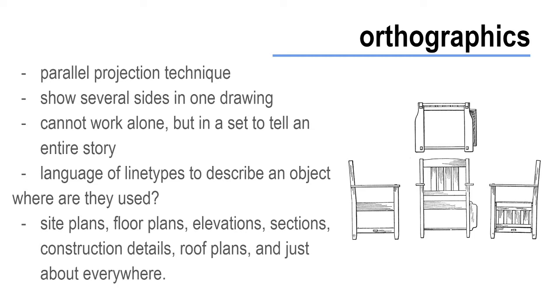Traditionally, it is 3 views: our front, our top, and then a single side view. We can unfold an object to show 6 views in total. All objects have a front, a back, a right, a left, a top, and a bottom. So you can show 6 different sides of something, but traditionally we only show 3, often because you just get repeated information from other views. For instance, with this chair, I don't really get any extra information from this side view, so I don't need to have it there.